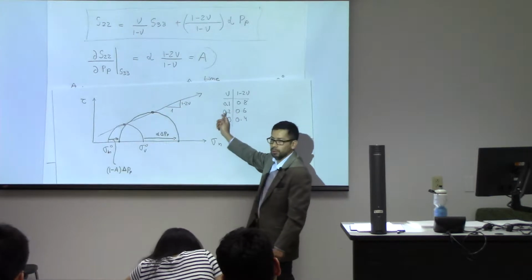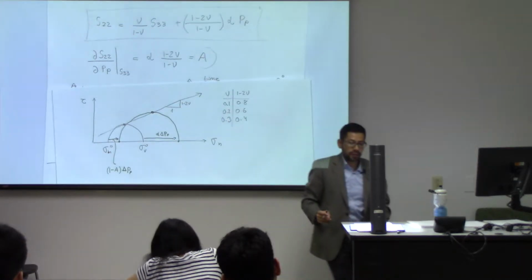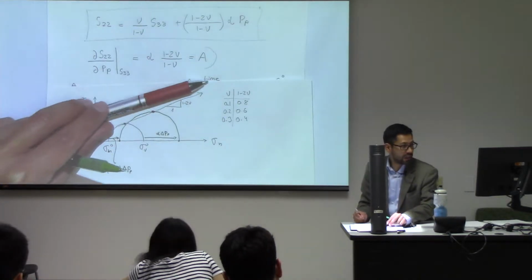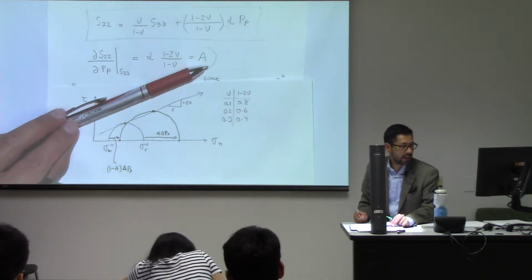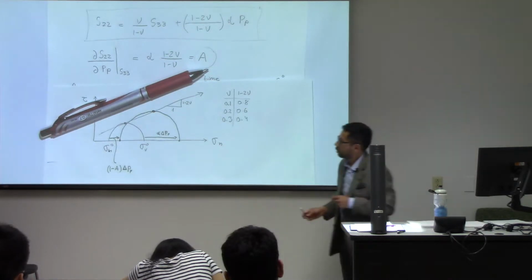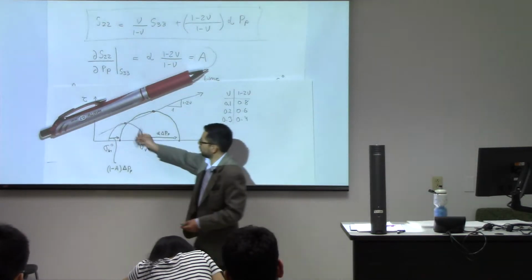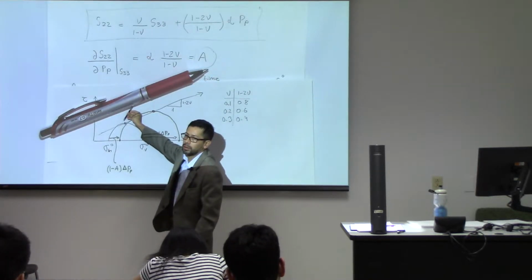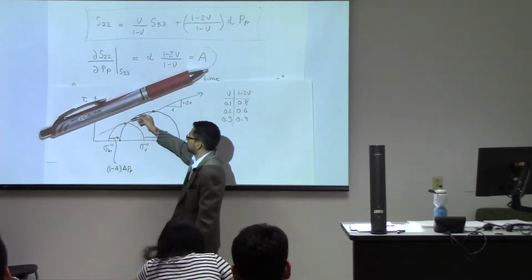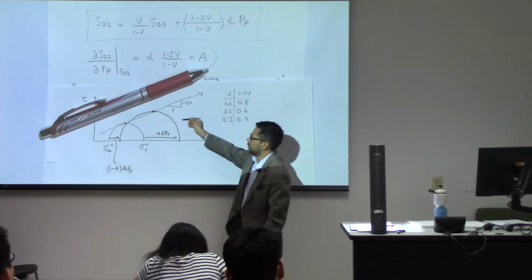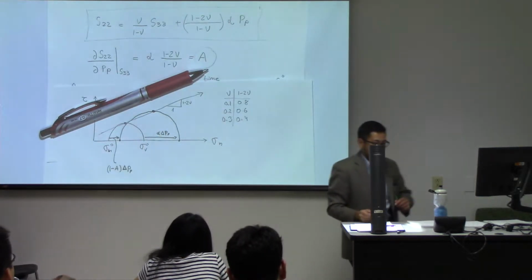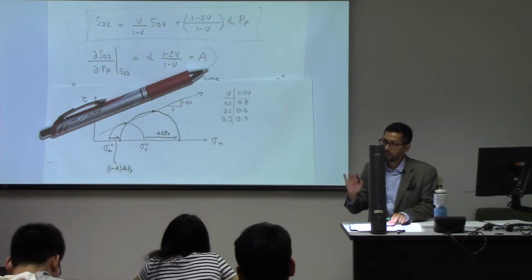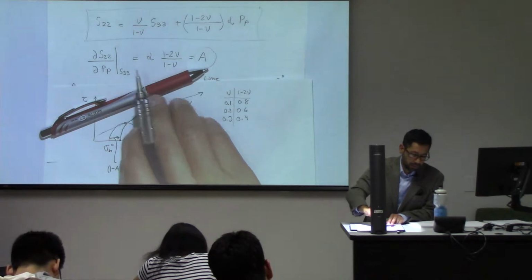If you have a very small Poisson ratio, that could mean that, let's imagine that you had a shear failure delimited by that line. If you have a small Poisson ratio, your stress path is going to go like this, and it's going to run into the shear failure. If you have a large Poisson ratio, it's going to go mostly in this direction. And I don't want to draw the line over here because it would be too many lines in the Mohr circle.